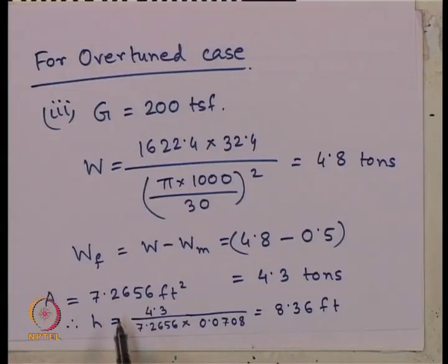Now, your horizontal dimension in the two directions x and y and the height are disproportionate, isn't it? So, as a good designer, what we should do? Remember what we said earlier, this A is minimum A to be provided. It is not necessary that we have to keep the clearance of 15 centimeter only, we can keep more clearance.